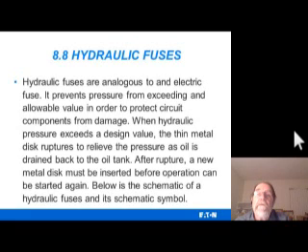Now, hydraulic fuses are analogous to the electric fuse. It prevents pressure from exceeding allowable value in order to protect circuit components from damage. When hydraulic pressure exceeds a design value, the thin metal disc ruptures to relieve the pressure as the oil is drained back to the tank. After rupture, a new metal disc must be inserted before operation can be started again. So it's like a fuse because it blows when the pressure gets too high.